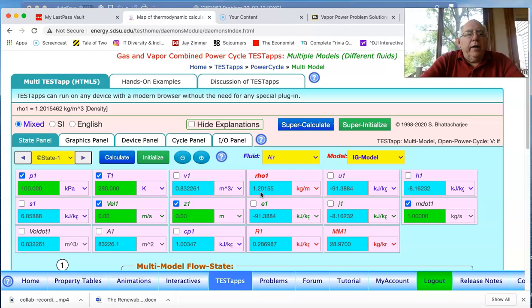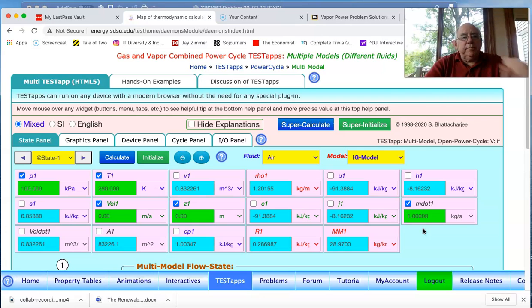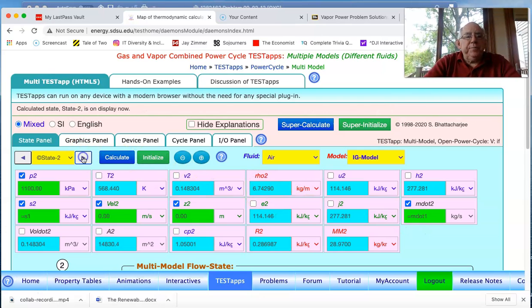So again, on the left side, we have the incoming air into the compressor. The conditions are given here, 290 for the temperature of the air and 100 kPa. Notice that I assigned an m dot equal to 1. State 2 is the isentropic work that's required by the compressor up to this pressure.